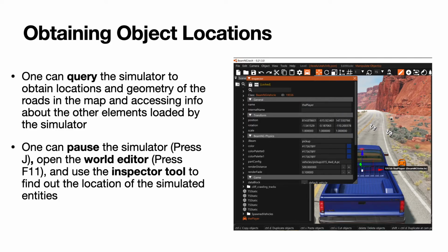Luckily, there is a way to understand what's going on, and the way is to start and load the scenario that you want to load, pause the simulation by pressing J, and open the world editor by pressing F11. What's the world editor?